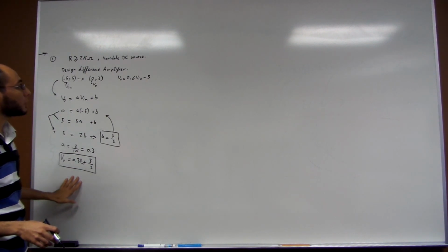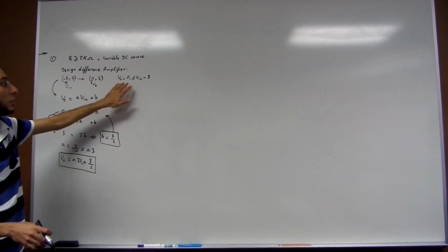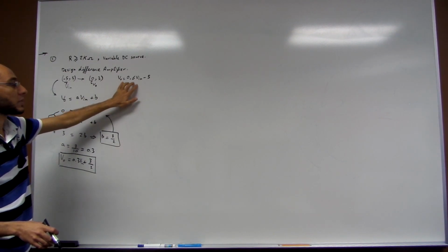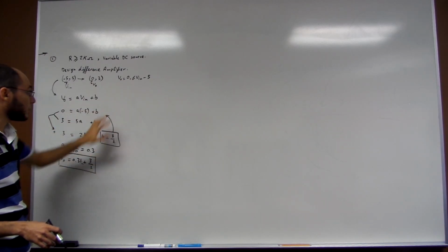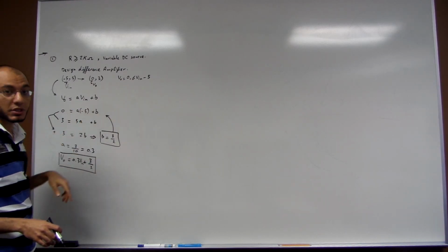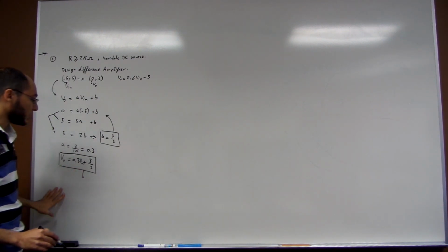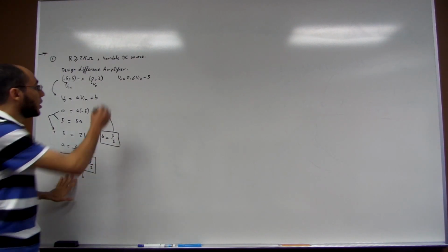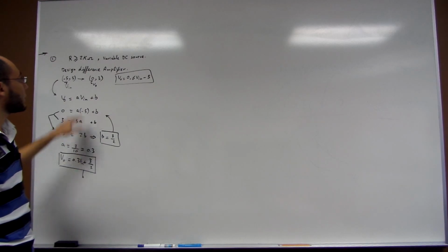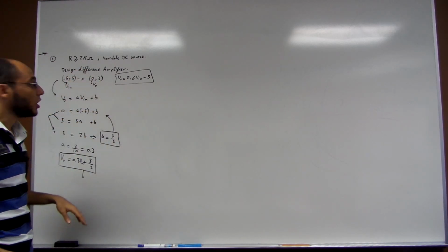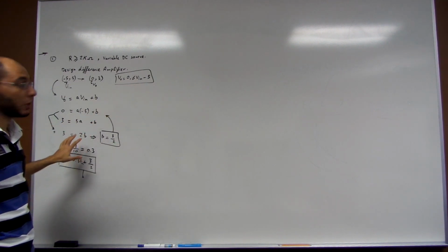So if you're given a problem like this in an exam, and you're given some kind of contradiction between these two results, then you can pick any one of these two equations and try to implement it. You could work on either equation, which means you need to design a difference amplifier to implement it. So basically that hint was supposed to help you.